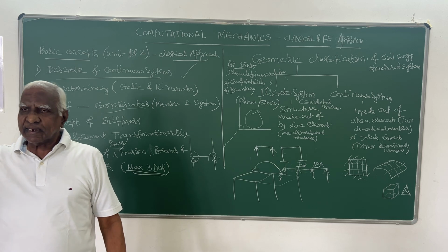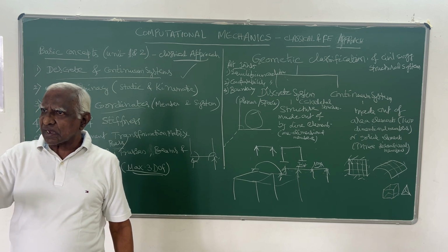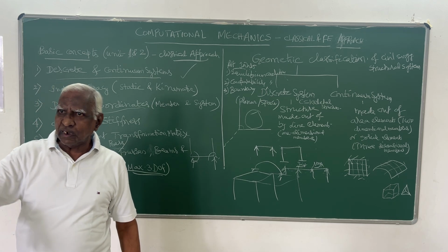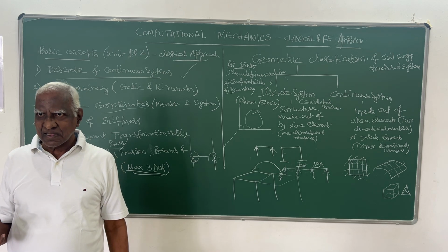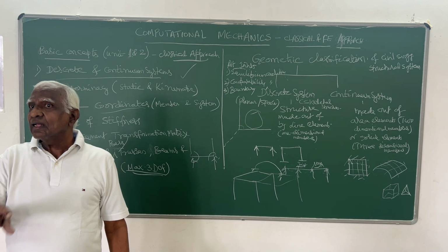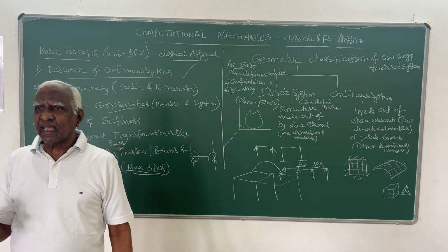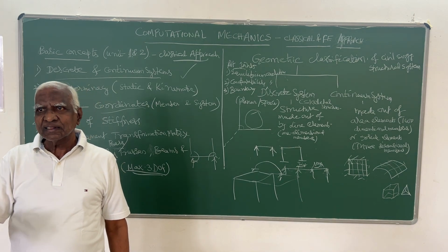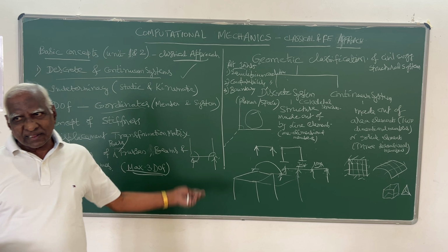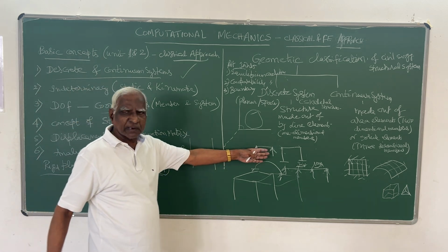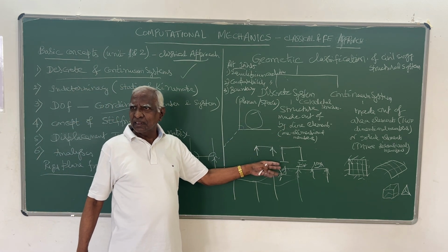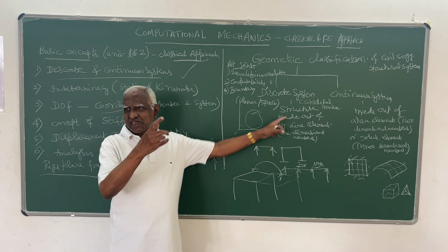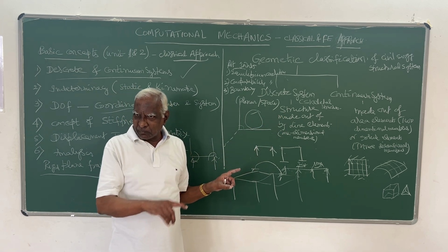Displacement may be in any direction, but for analysis purpose, we have to resolve them only along 3 axes, right? And the displacement along all the 3 axes should be 0. That is, in other words, forces in all the 3 directions should be 0. The third direction is not considered here because it is a planar structure. That is, Fx is 0, Fy is 0, only 2 directions should be 0.